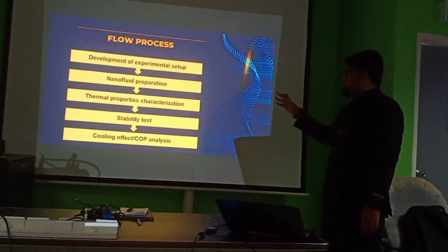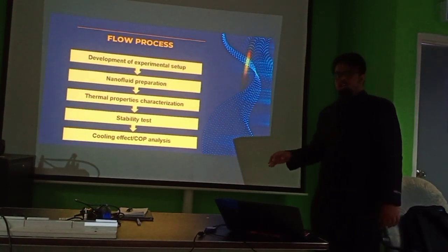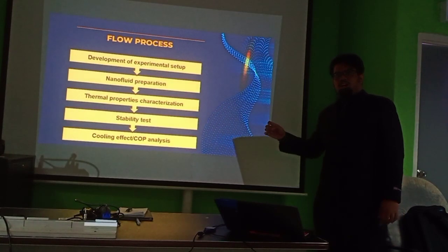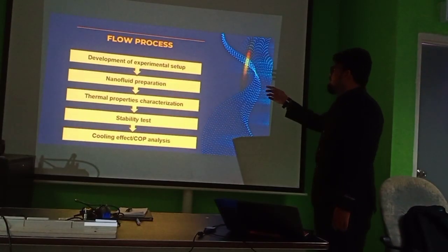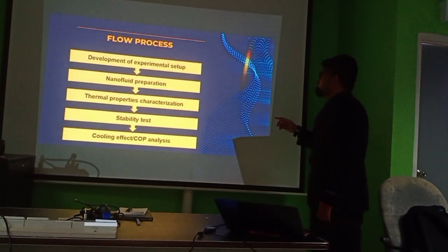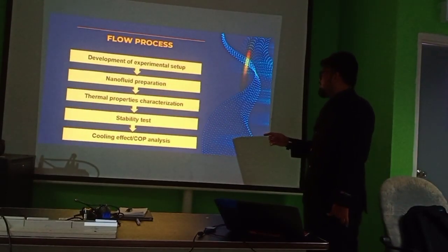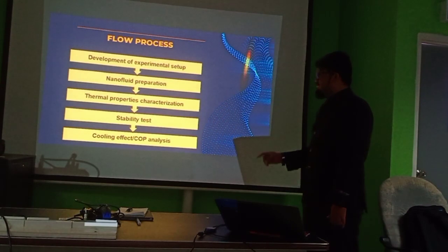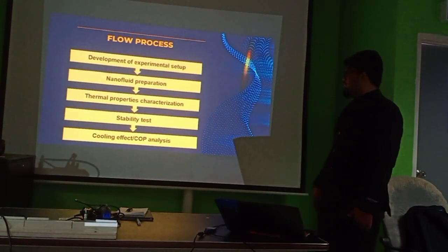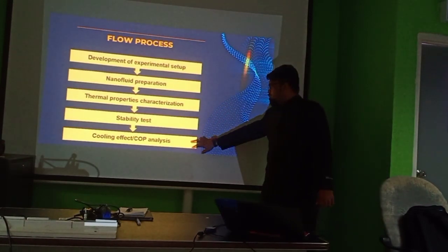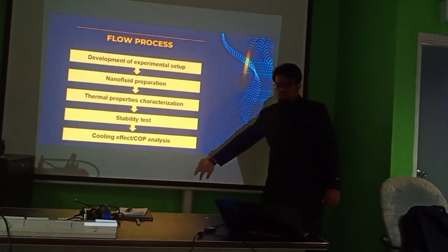This is the general process flow of the method that we conduct. First, development of the experimental setup, nanofluid preparation, thermal properties characterization, stability test, and then we can obtain the cooling effect or COP analysis.